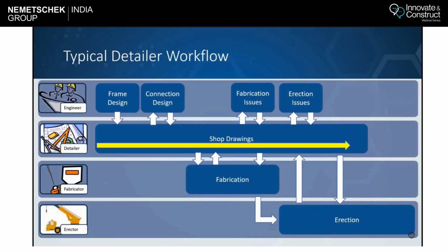But if you have an inbuilt connection design software in your detailing system, you can just place the stick members, and the connection calculation report you can directly send to your fabricator or your connection designer. Since it is code compliant, 99% the calculation will get approved, unless there is a framing situation or any special requirement. Even if there are changes, there might be 20 or 25% changes. You can apply the changes into your model and send your approval package for further review. But if you do not have that system, you have to wait for the fabricator or your designer till their input comes, and you cannot place any members.